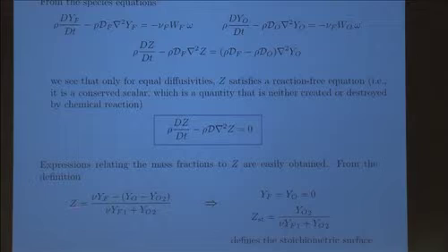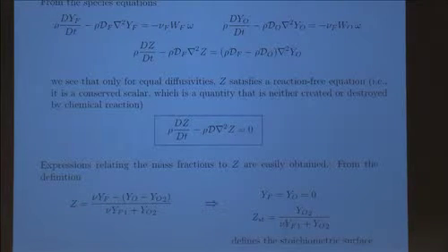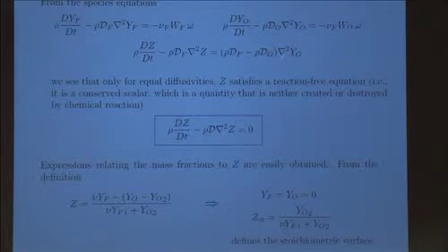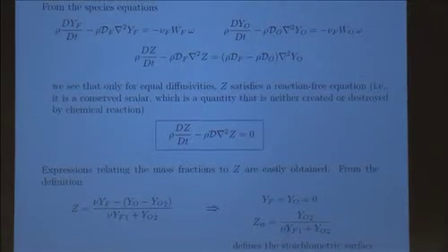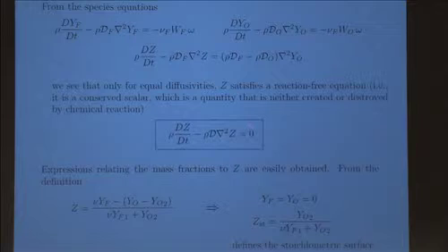That's a constant. So when you take the derivative, it's like a coupling function. So it's one of the coupling functions. Okay? So if it's a coupling function, then when you construct the equation for it, it will have a 0 on the right-hand side. In other words, it's a conserved scalar. So the equation for Z is just convection-diffusion equal to 0.